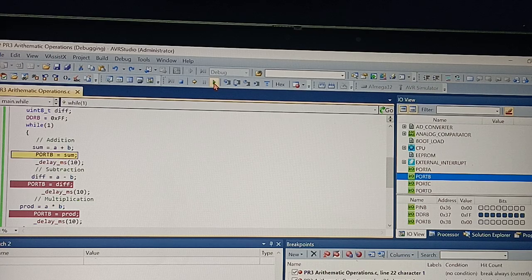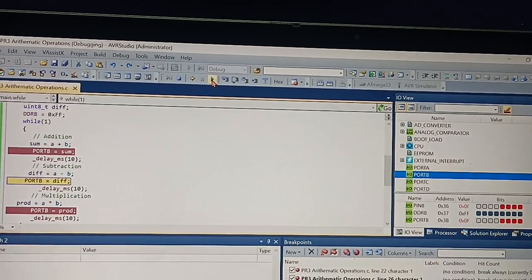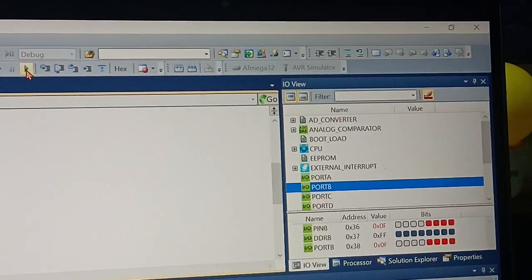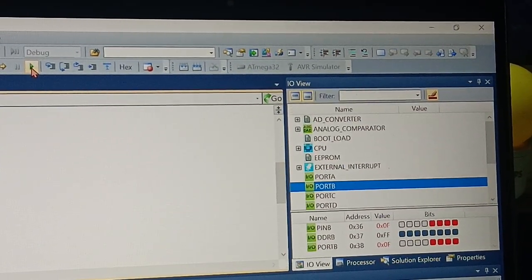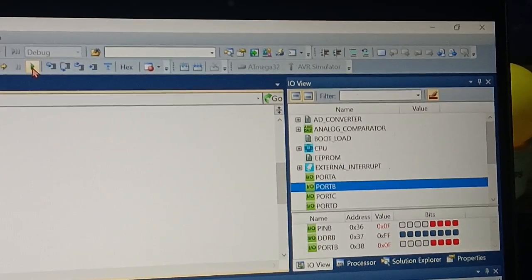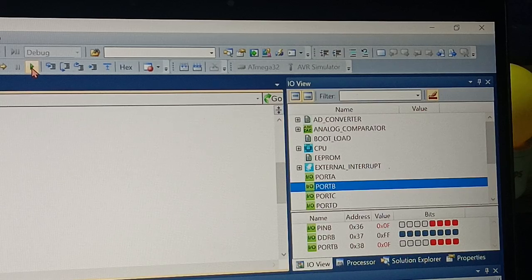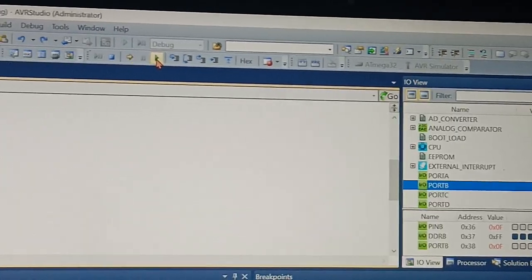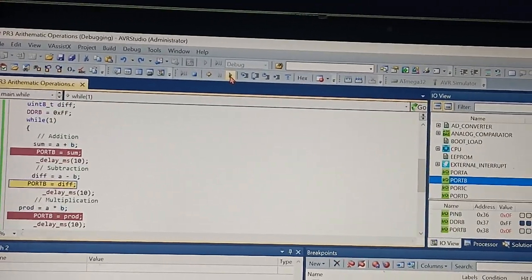It has to be executed till the first breakpoint. Now see, the result shown over here is 0xF. You can see the result over here, it is showing 0xF because we were adding 10 plus 5. 10 plus 5 is 15, which is in decimal. So in hexadecimal, it has to be F. So our answer is correct. It has been executing exactly.